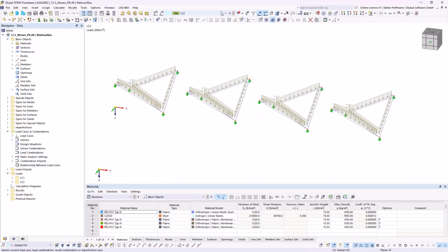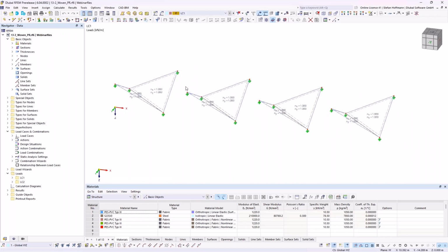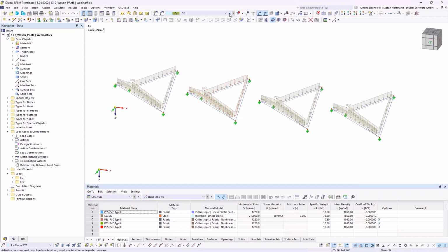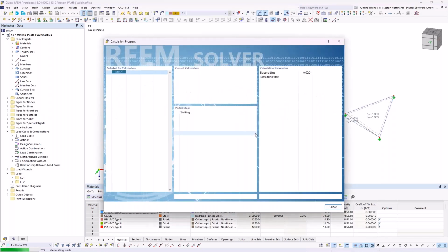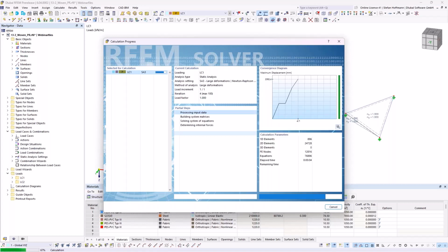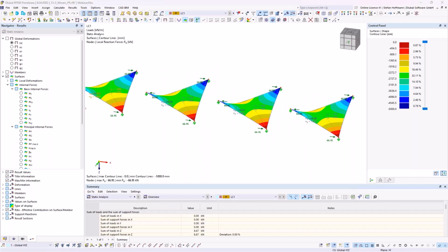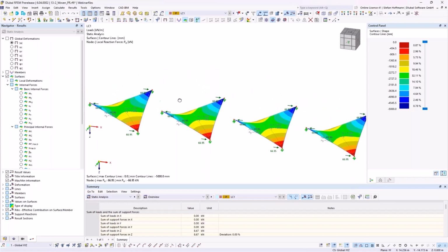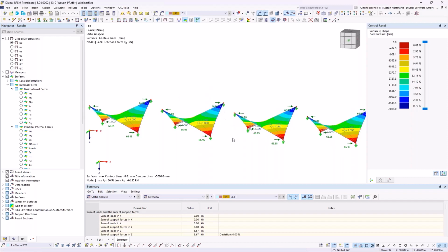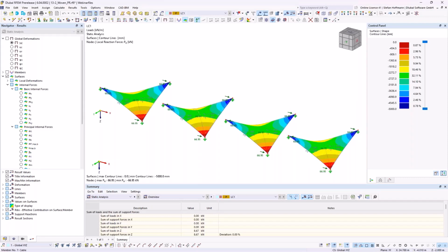And then there is a pre-stress we are giving, just a normal symmetric pre-stress into local X and Y direction with the standard method, so nothing special. And we want then to load it with a vertical load, because doing the pre-stress, so the form finding for the structure, we most likely define the shape we want to reach with our inner forces. So the material properties will not play a big role. And we will receive then a shape, a contour shape, which is similar, even if we use different material models.